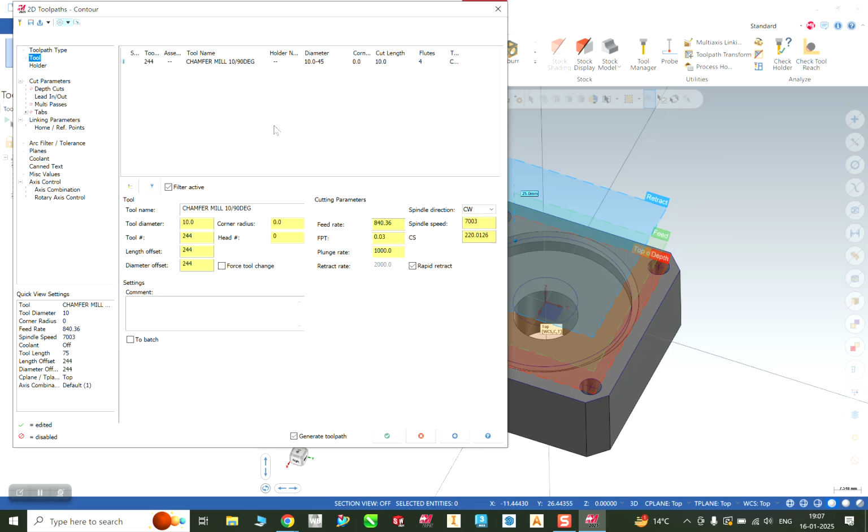Normally when you cut chamfers for these products, it is 2 into the angle. Okay, span distance into angle. That angle is 45 degrees, and we only need to give the distance now. Okay, sir, the angle is already given in the tool. If we need to change the angle to 30 or 60, what do we do, sir? We need to change it at that point. If we need 30 degrees, yes, we need to change it to 30 degrees in the tool specifications.